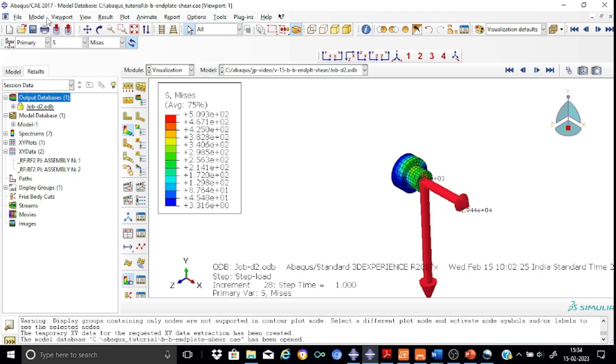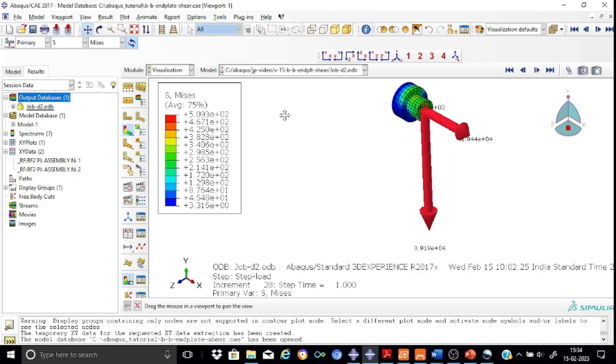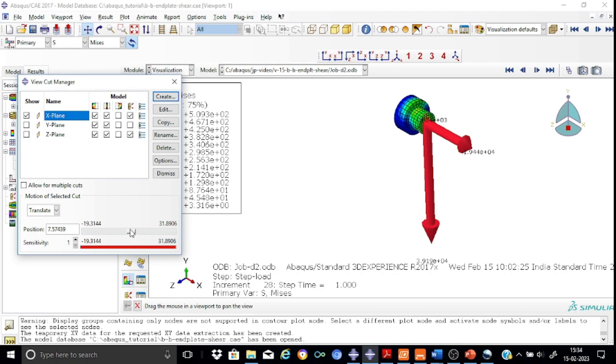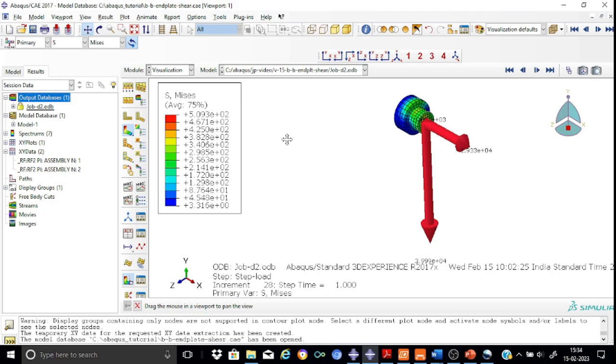So we find that the shear, for example, in this selected bolt is of the order of, let me just move this section a little bit up or down. Yes, it's of the order of say 40 kilonewton. For M20 we have got a shear capacity of the order of say 90-95 kilonewton. So we don't have any problem as such in the shear capacity demands for the bolts.